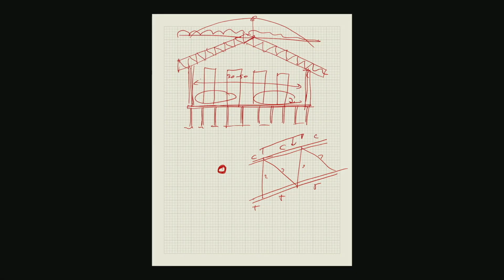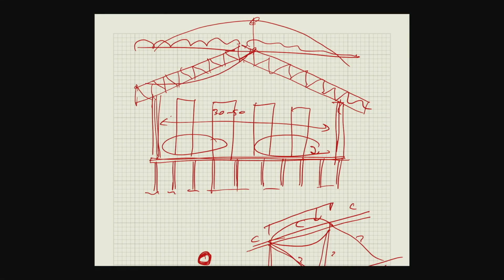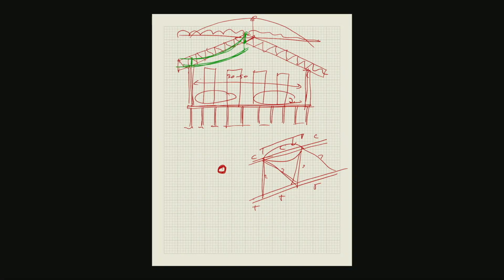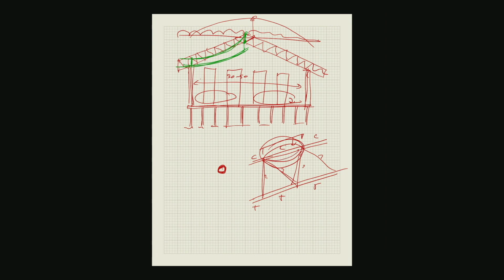The point is that the global behavior is not considered. You might think that you have the diagonal like this, so the buckling will be just about this, but no, it could buckle like this. It could buckle like this, right? If you brace at the middle part, the midpoint here, you might have your roof truss buckle like this. So things like this are quite interesting, and sometimes the analysis or the design is simplified too much, and you might not get the behavior that you wish. You think that okay, it's going to buckle with the full buckling length, half side buckling like this, but no, the global behavior is coming up in that view.